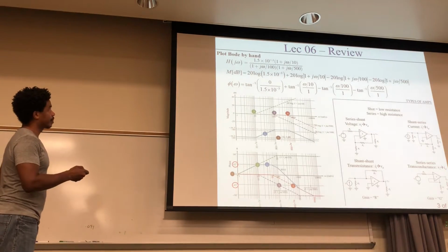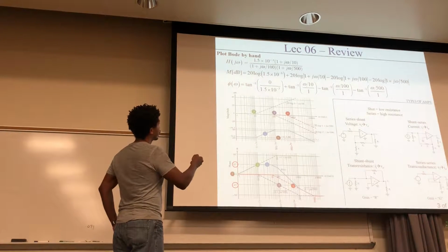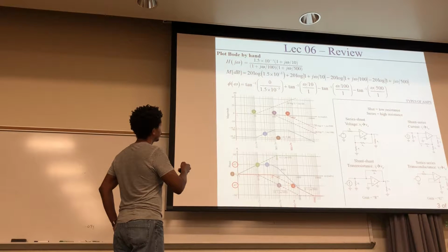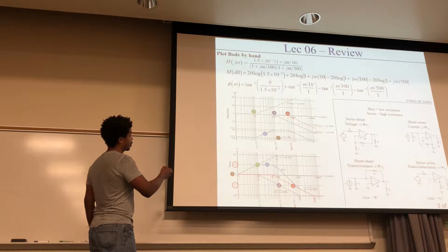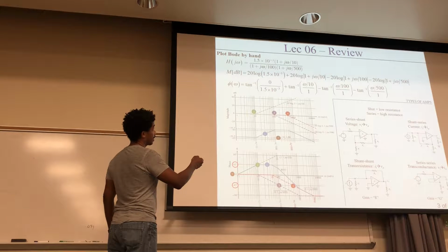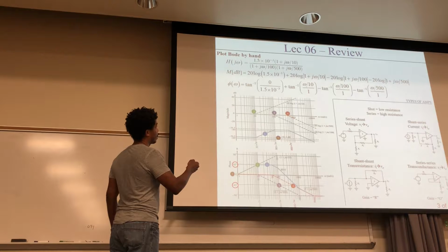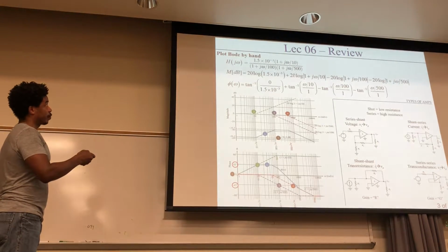Okay, so that's the thing with these right here, right? And for each one, you just plot it out. So this right here is this line. This one right here is this green one right here, which has a cutoff of 10. It just keeps going up like that. And remember, the reason why it asymptotes to 0 is because on these things right here, this value gets negligibly small, okay? Because omega is getting very small, and so you just have the magnitude of 1, and that becomes 0 right here. As you're going off this direction, right here, then you're getting 20 decibels per decade.